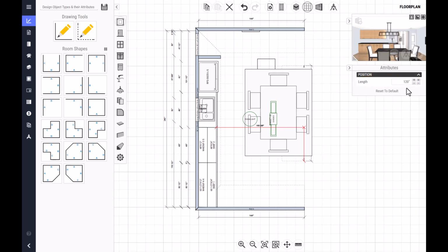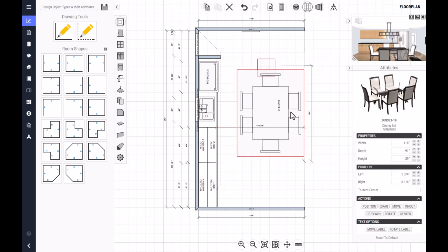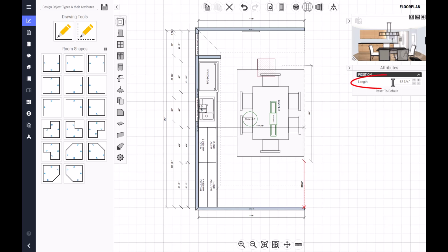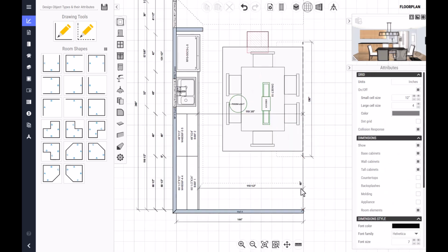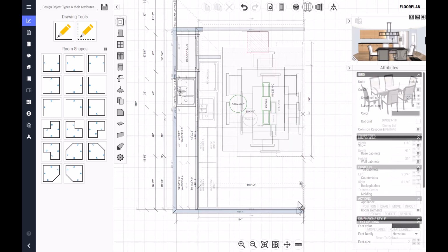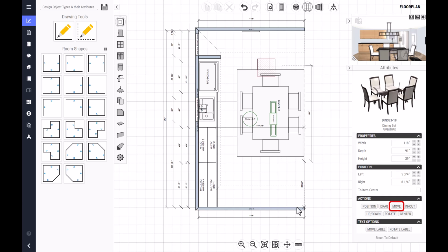If you need to adjust the starting point for the wall, we can select vertical dimension this time. Again, selecting the hidden wall first, and then selecting the south room wall second. Select the dimension, and in the length text box, we will type in a value of 60 inches and hit the Tab key. Now, if the placement doesn't need to be so precise, you can always use the Move Action tool to locate it vertically or horizontally in the plan view.